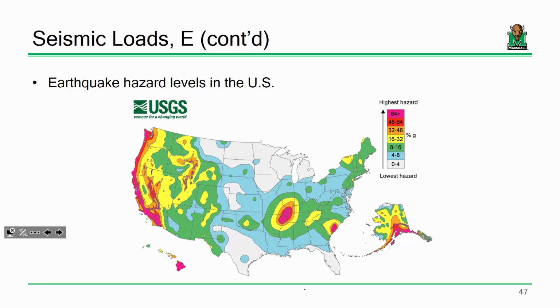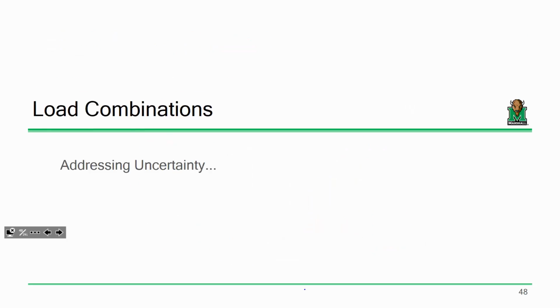We distribute those seismic forces to the floors and then open up RISA and do our analysis. The only thing you have to be careful of is where you're getting your accelerations. It depends on where you're at. Obviously, we're going to have a different hazard level for earthquakes in West Virginia than we are in Nevada or California. Luckily, there are some really nifty online tools you can use to assess your ground accelerations and go from there. Sound good?